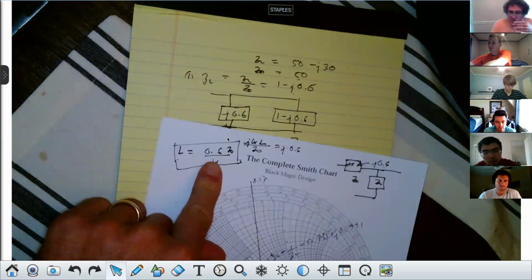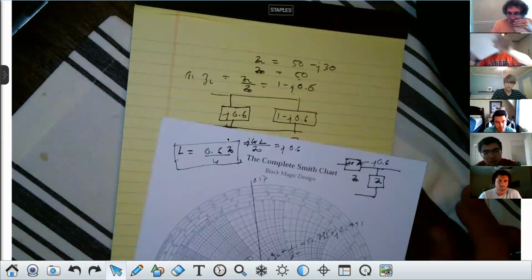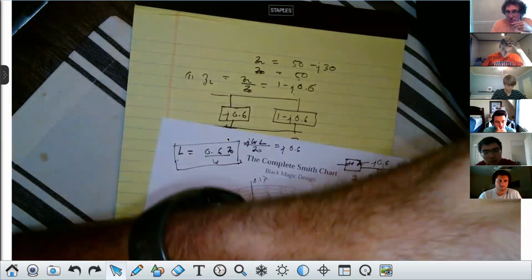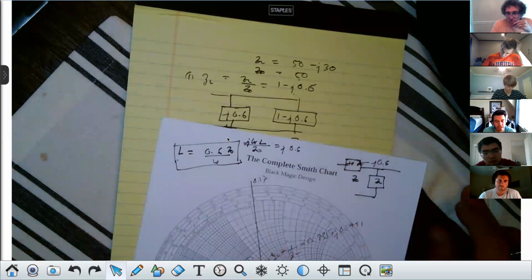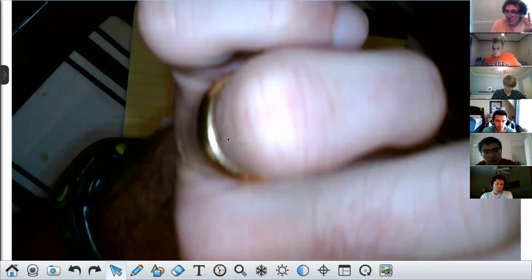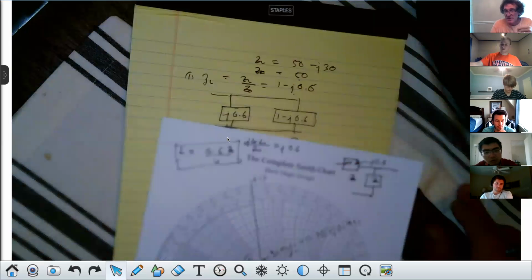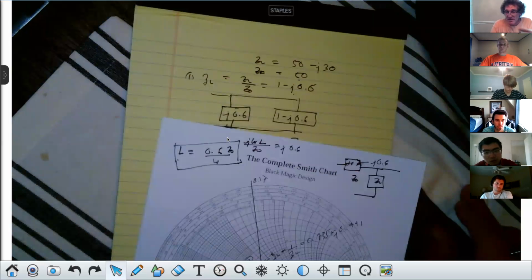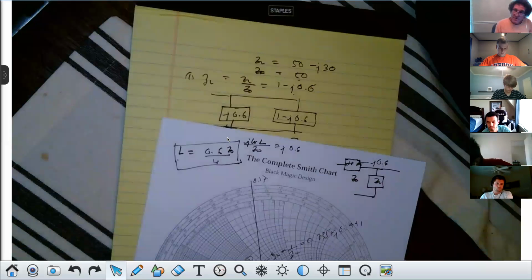So the roles for capacitors and inductors are reversed when we go in admittance. They're 1 over, right? Admittance is always 1 over impedance. So if we're going in series and we want to put a capacitor in, we look for the 1 plus j something. Well, hold on for a second. If you're doing anything in series, you're doing it in the normalized impedance domain. If you're putting anything in parallel or shunt, it's the normalized admittance domain. Those are the 2 key things. And a capacitor will always have a positive admittance sense in j and a negative j impedance sense. So opposite for the inductor, but those are things that are fairly obvious.